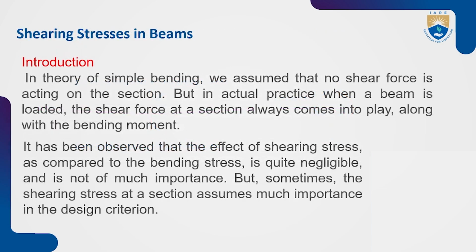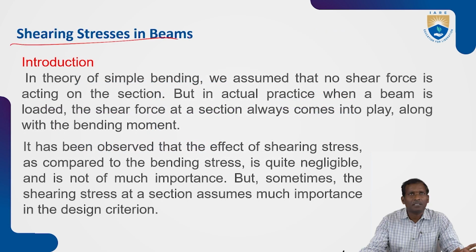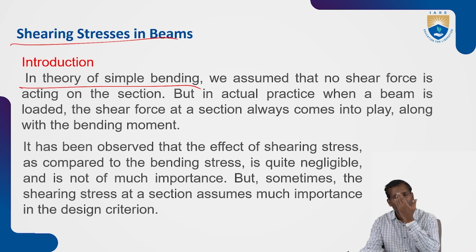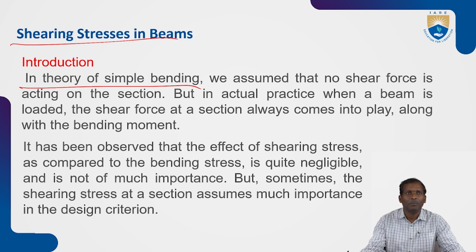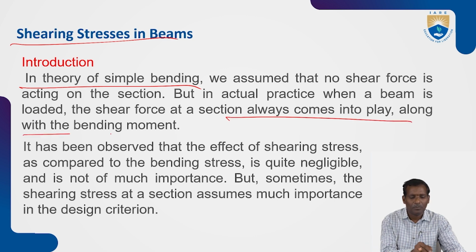Now another stress, that is shearing stress. In the theory of simple bending, we assumed that no shear force is acting on the section. We assumed this while deriving the simple bending equation. But in actual practice, when a beam is loaded, the shear force at a section always comes into play along with the bending moment.